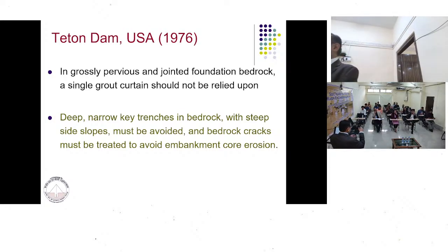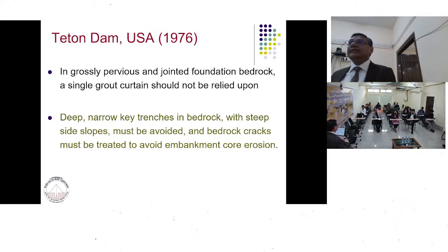And we also feel that, okay, you do a grouting here, then you do a grouting here, then you do a grouting here, and then you do a permeability test. And if the permeability test is not showing any flow, this means we assume that this grout and this grout have met each other, and we have a continuous impervious line of grout. So it is the most unengineered method of assessing the efficacy of grout. In case your permeability test goes wrong, your whole grout design is wrong.